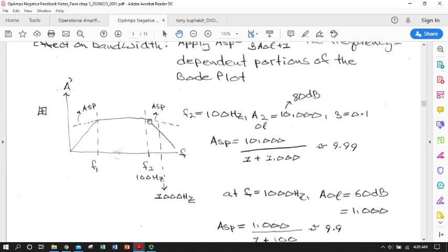And I'll give you a hint from this graph. The solid line here represents our 20 decibel per frequency decade loss as we go out in that lagging region beyond the midband and increase our frequency. This little dotted line labeled ASP is a little bit of a schematic representation of what our series parallel negative feedback should be doing to the gain, and that should be a prime, because all of these gains on this particular plot, of course, are decibel.